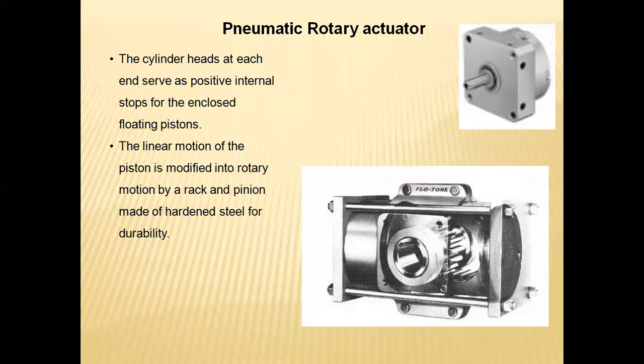As shown in the figure, the cylinder heads at each and every point serve as positive internal stops for the enclosed floating pistons. Moreover, the linear motion of the piston is converted into rotary motion by the rack and pinion, which is made of hardened steel for durability.